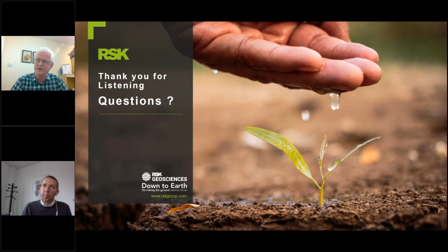In the same way as if you're loading a soft clay, then you'll have a consolidation with time, and it's not going to be in weeks or days, it's going to be months and years. So it's the same with the moisture variation, really, that it isn't going to be a short-term thing, which makes it hard to research it.